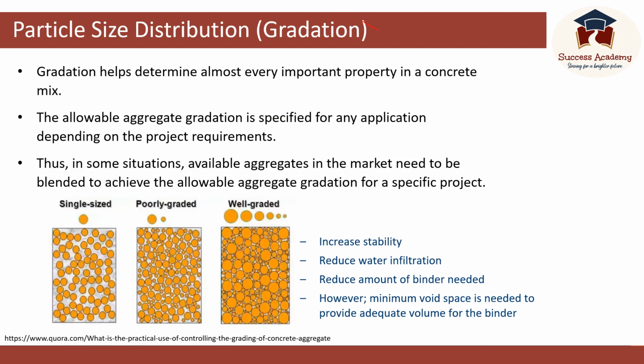Let's start with the gradation or the particle size distribution. Gradation helps determine almost every important property in a concrete mix. The allowable aggregate gradation is specified for any application depending on the project requirements. In some situations, available aggregates in the market need to be blended to achieve the allowable aggregate gradation for a specific project. You can see some examples here.